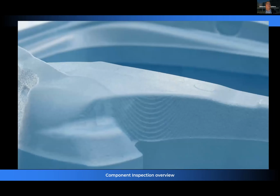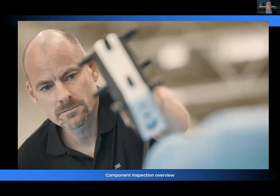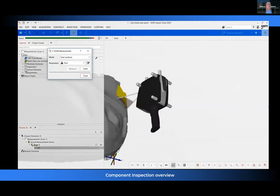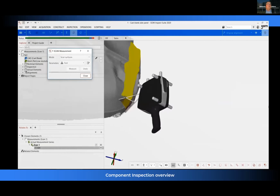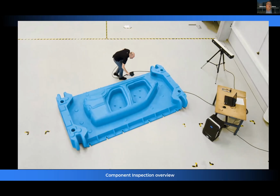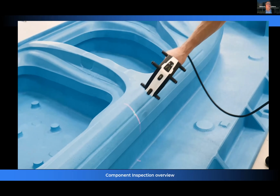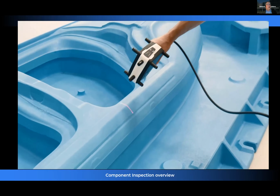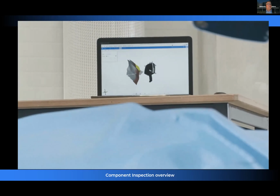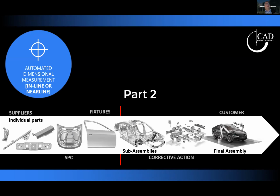in the hand scanning market, one of the things that you'll notice about this part is that there's no stickers on it. There's no markers. There's nothing like that. The guy has a scanner device in his hand. He's capturing hundreds of thousands of points a second in this case on a very large part. This is obviously for a tool. And as long as the part in his hand can see the optical tracker, he can create high quality, lots of data very, very quickly. And this is again just a portable metrology tool that you might see out there in the market.